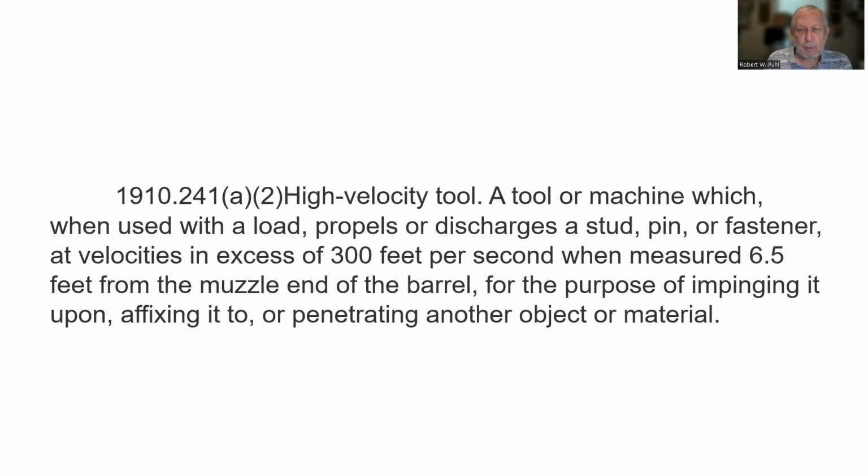High velocity tool, a tool or machine which, when used with a load, propels or discharges a stud, pin, or fastener at velocity in excess of 300 feet per second when measured 6.5 feet from the muzzle end of the barrel for the purpose of impinging it upon, affixing it to, or penetrating another object or material. So the first one has whatever is going to be driven up against the target, and this one's going to shoot it at the target.